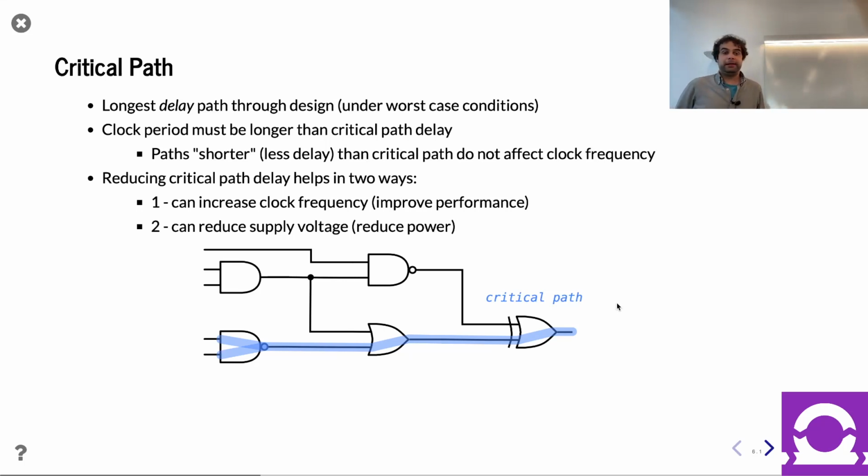Now, people may be asking about things like, what about overclockers, right? Well, overclockers are reducing the clock period by increasing the clock frequency. And yeah, they're seeing how close they get to that critical path. It may turn out that the vendor of their hardware had a lot of margin there, so they can overclock and it works just fine. It may turn out that they overclock too much and it stops working. Or it may be in an in-between state where technically you're not meeting critical path latency anymore, but the critical path happens really rarely, or if the critical path is violated, it doesn't cause the computer to instantly crash. And so you can live along for a little while.